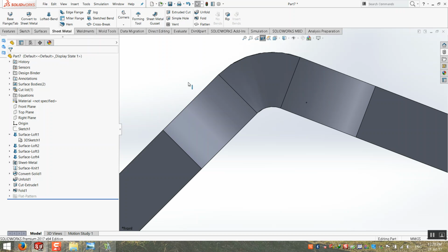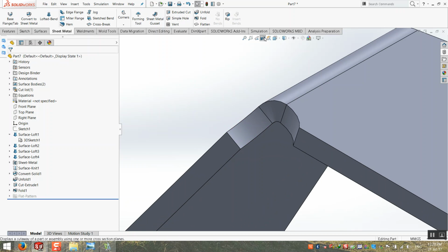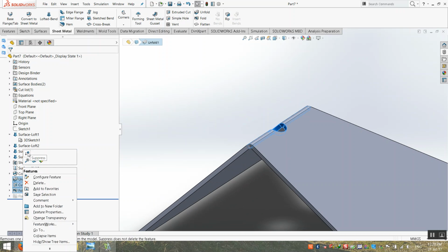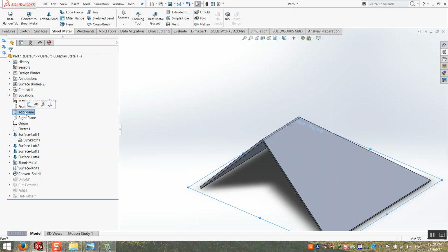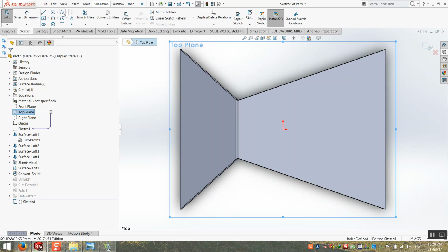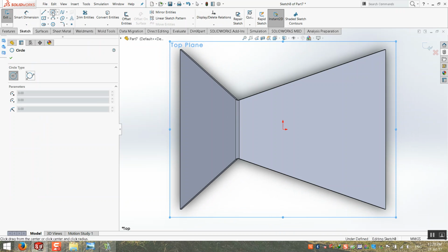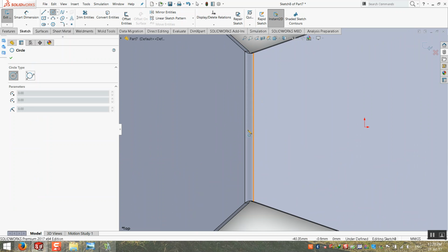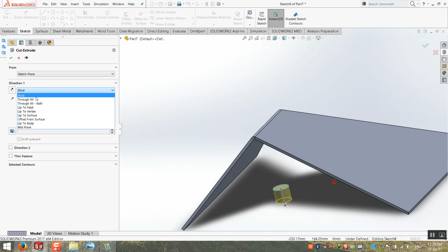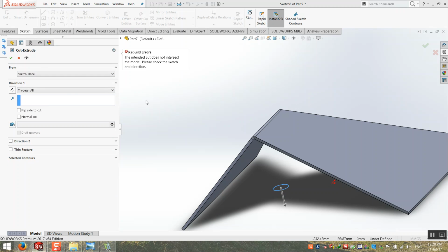All right. How can you identify it in the drawing? You can identify the steps of manufacture in your drawing. So I don't need to make this feature like that? No. Normal cut. Just a circle, without unfold and fold. Just through all from here.